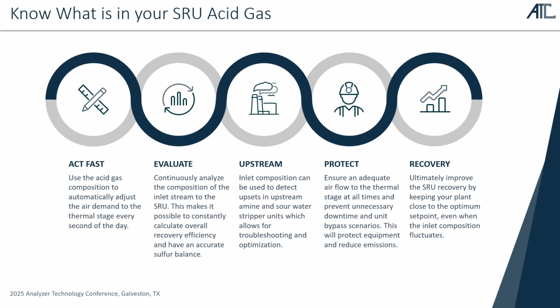Third, we want to create some residence time between the sample and the valve that responds to a change in gas composition. So we prefer the sample point to be as far as possible upstream of the sulfur plant. That could either be on the top of a reflux drum in the amine regenerator, on the top of a sour water stripper column.